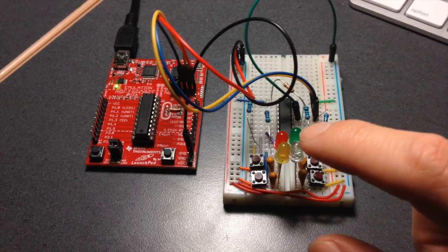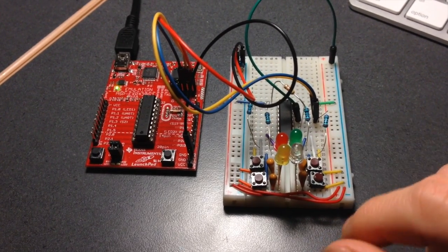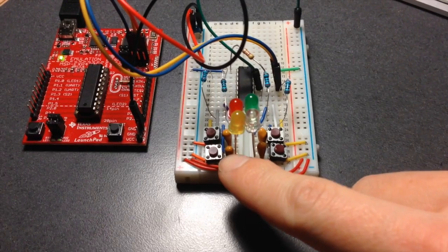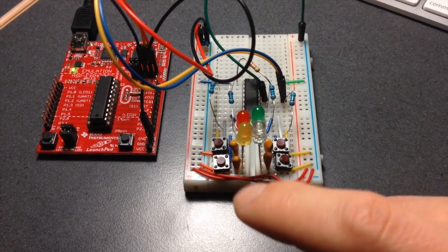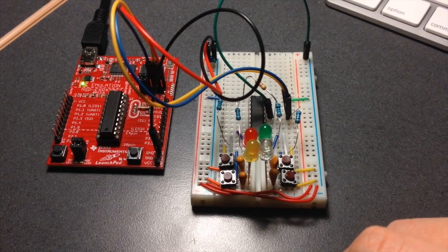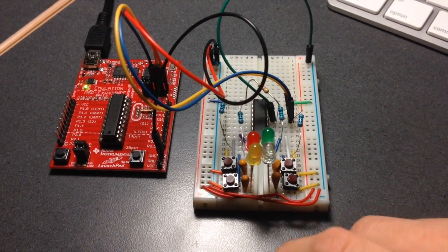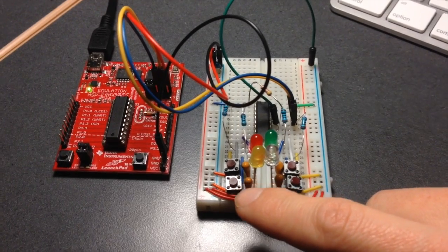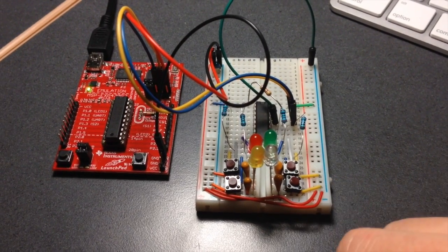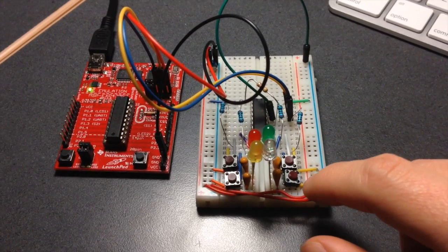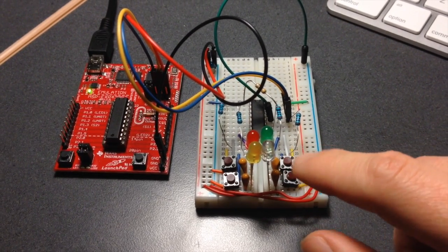We of course have a bunch of resistors for those LEDs, but something interesting that we have are these capacitors, which in tune with the internal resistance on the MSP430 create an RC circuit, which is essentially a low-pass filter, and that allows these buttons to be hardware debounced, so that when the user clicks a button, it doesn't register multiple presses if the button is not the most precise.